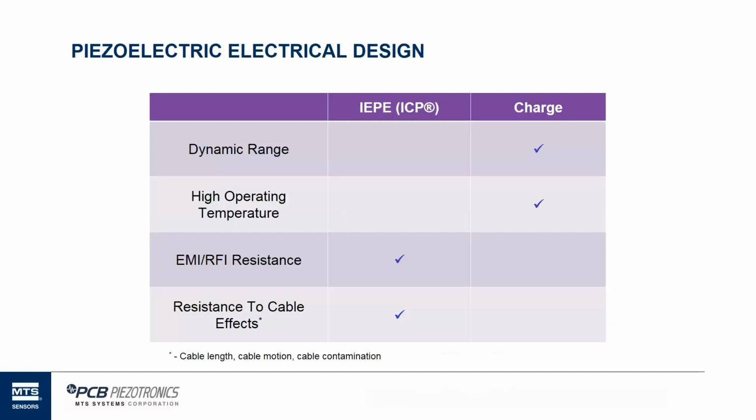As soon as you convert that to a low impedance output signal, whether it's on the inline converter or on the lab style charge amplifier, you can run dozens, hundreds, thousands of feet of low impedance cable to the measurement device and it won't have an effect. That's not the case with charge mode cabling. You're going to see high frequency degradation, especially on those long cable runs.